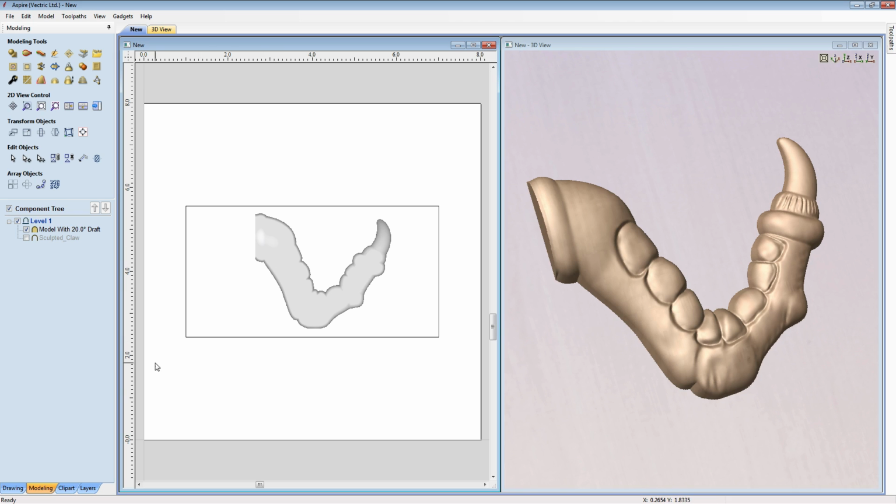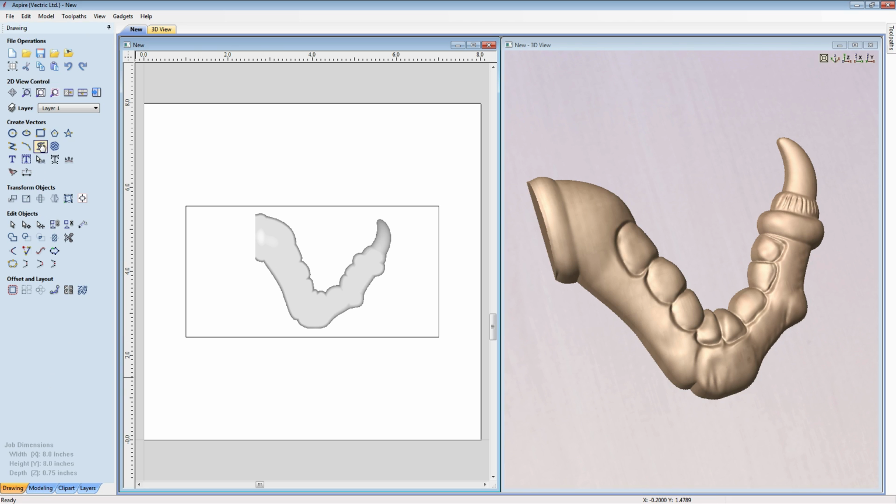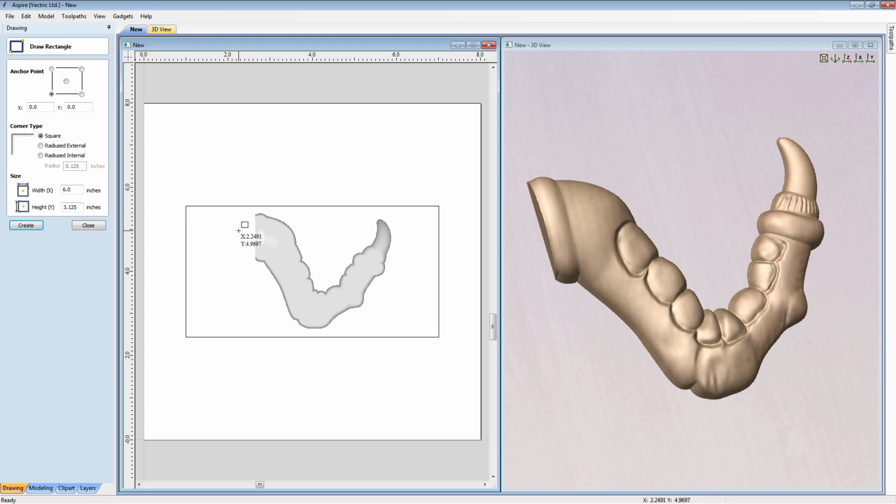Now we're ready to create the bolt location. Back to the Drawing tab. I used M5 bolts, and so I decided I wanted to create a little cylinder or half cylinder that was 6 mm across in order for that to sit in. So I'm just going to sketch a rectangle here, and I want the width of that to be 1 1/8, which was the length of the bolt, and I say the height here I want to make 6 mm.